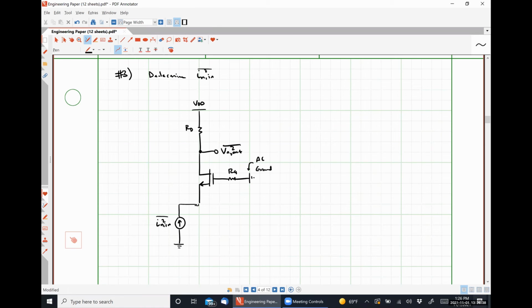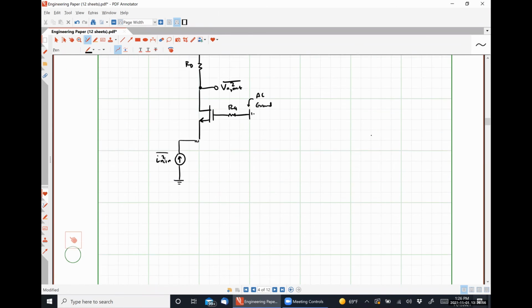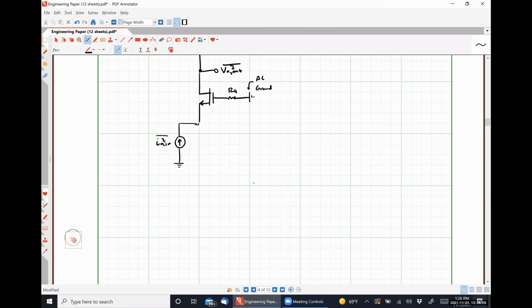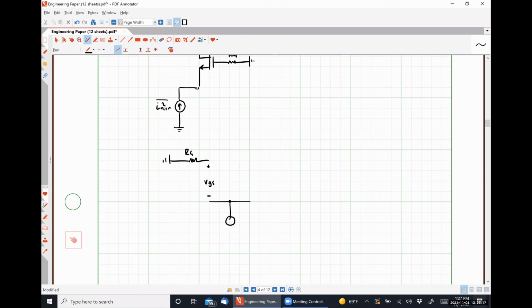So in order to make that happen, we need to know what the gain of the system is that converts that input current to that output voltage in general, right? So our small signal model on that end is going to look something like this, right? So we know that our gate terminal here is at ground, then we have resistor RG. Here's VGS. Now we're applying some input current. I'm just going to call it IN for the sake of argument. We don't have to carry around so many things.